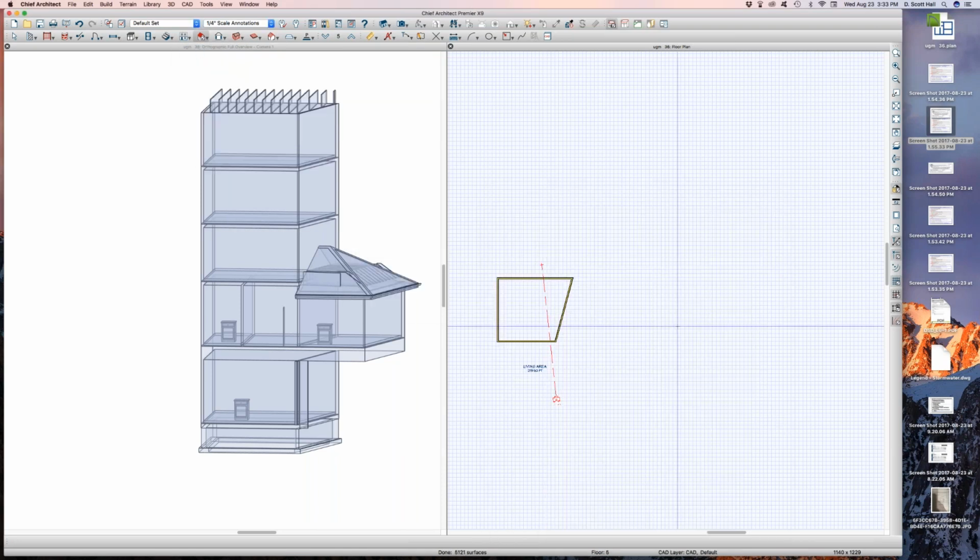Okay. If I change a floor level, anything above it moves. Nothing below it moves. Yes. This is why when you're editing floor levels like this, you should always start from the top and work down. Thank you. Yeah, that's the reason for it. I'm going to just say that one more time.